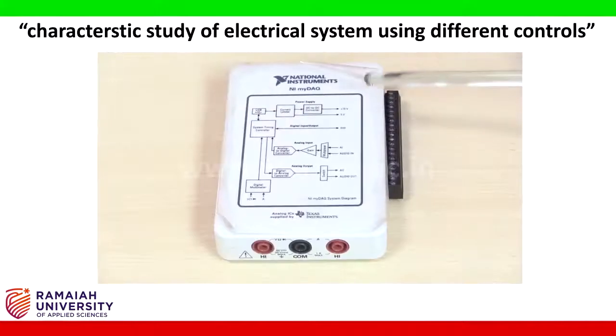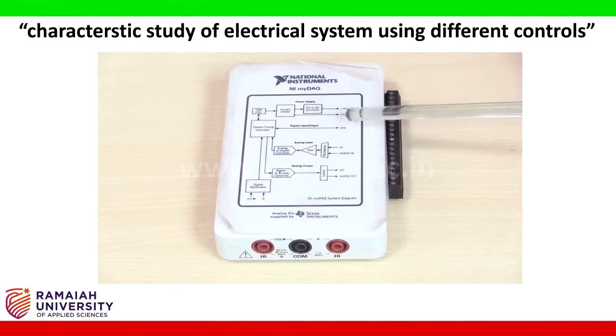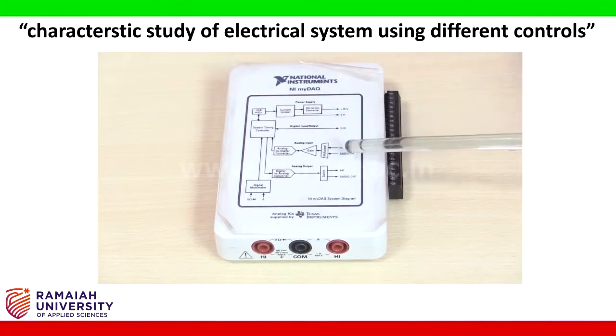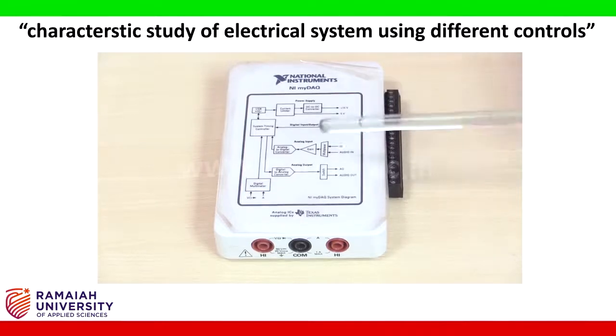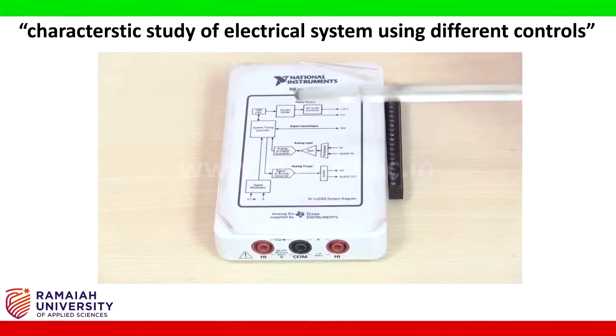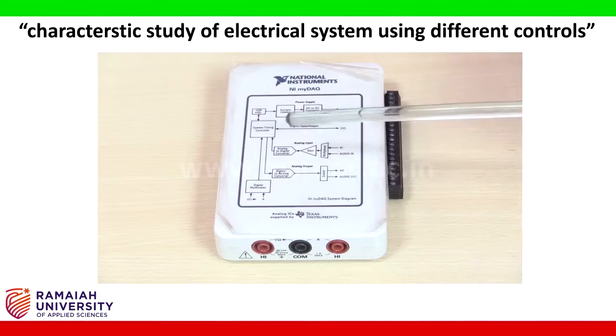Now we look into another important hardware which is nothing but the data acquisition hardware named NI MyDAC. This is really important in this experiment because whatever hardware output that we are getting will be interfaced to a PC using this data acquisition system. The purpose of this data acquisition system is to convert your analog input, which is received from the external world, to a digital output which can be communicated to your software or to your PC using this particular device.